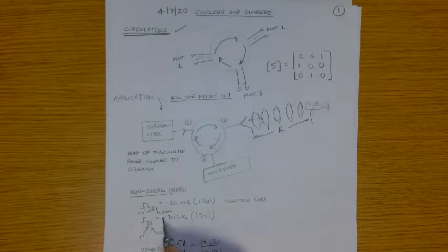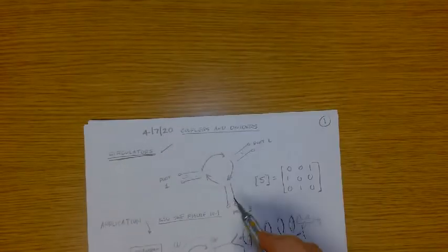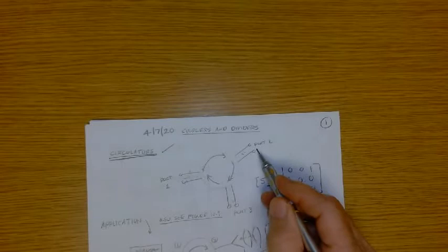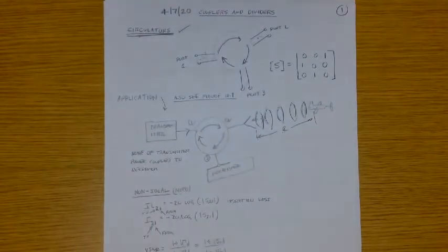Log of 0 is minus infinity, times minus is plus, and so we want S21 to be an insertion loss of 0, and we want an isolation of infinity, right? So we want this port to be isolated, this port to be fully coupled.